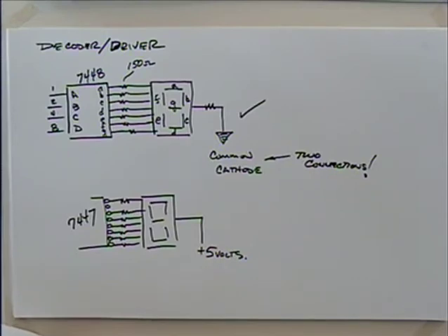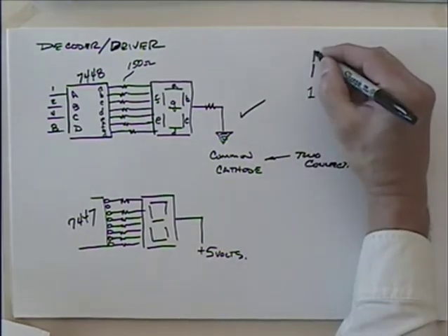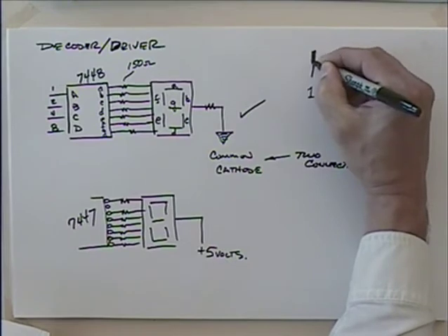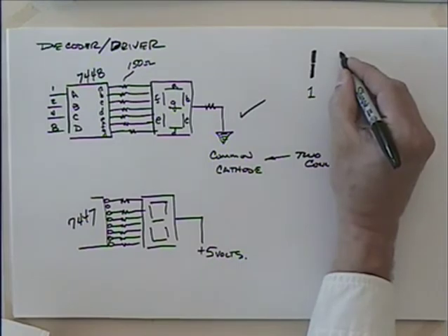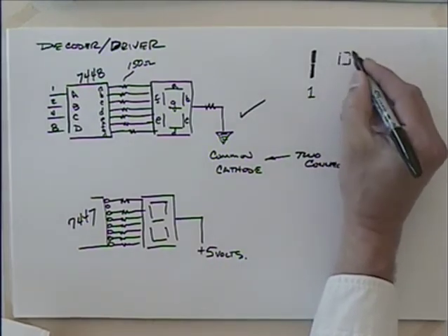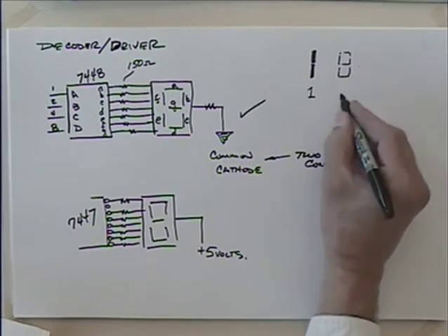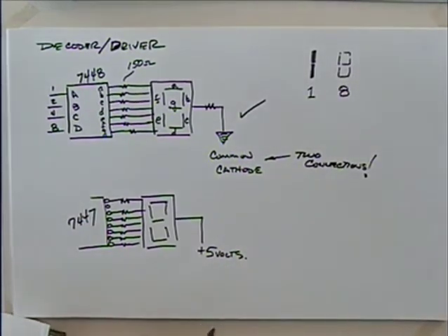Well, if you have 1 segment on, it's going to be really what? Really bright. If you have 7 segments, I guess maybe there's no use of 1. So if you have the 1 on, as in 1, it'll be really bright, won't it? Okay? So it'll look something like this, and you'll be burning up your LEDs. Whereas if you have an 8, it's going to be very faint, isn't it? Okay? So if you want a consistent brightness of the individual segments, this is the way to go.